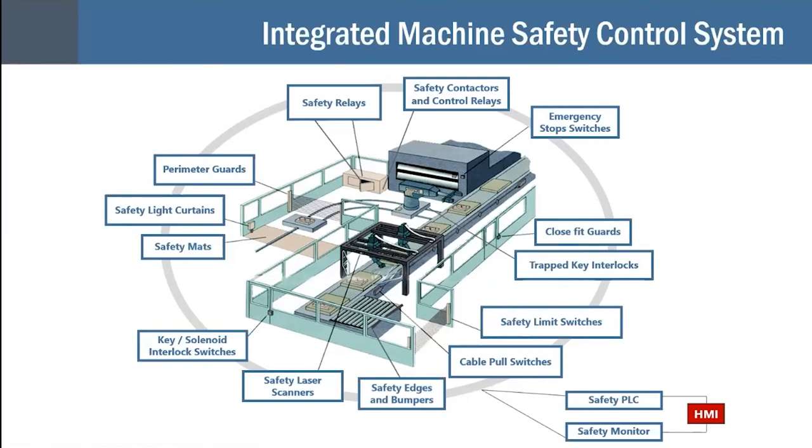This is more of an awareness thing. A safety control system is that interconnectedness of the elements of the guarding. It's important to keep in mind that a safety control system is only as good as the weakest link. If the components are not safety rated, then the system will not perform to the necessary level of control reliability that gets determined during the risk assessment.